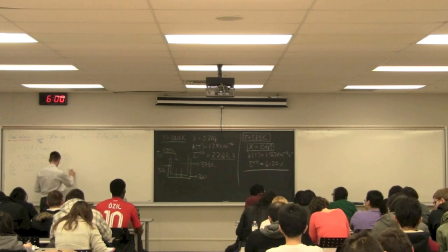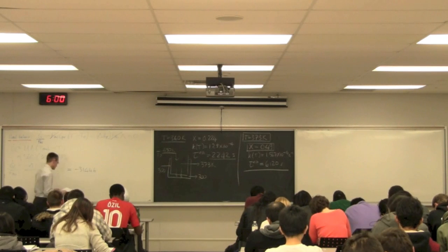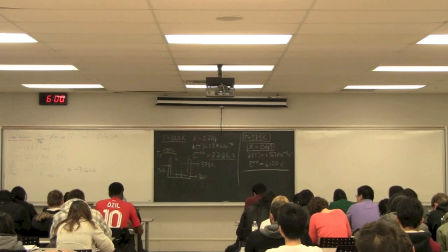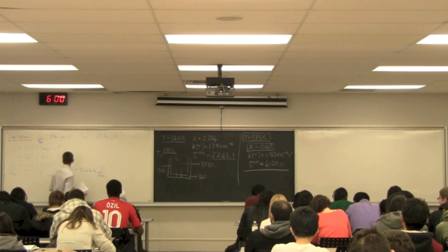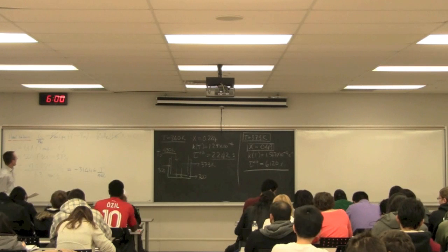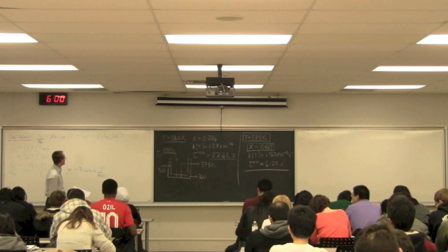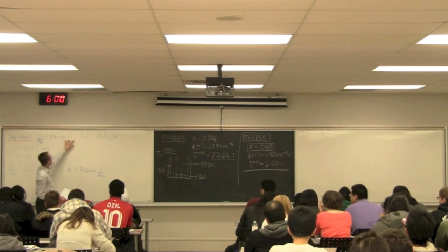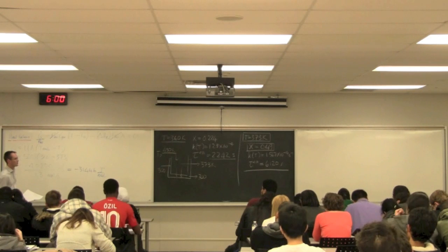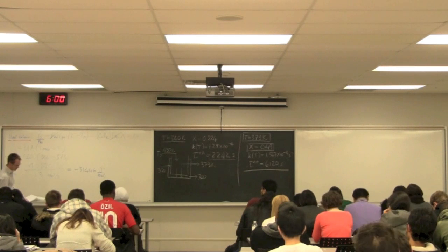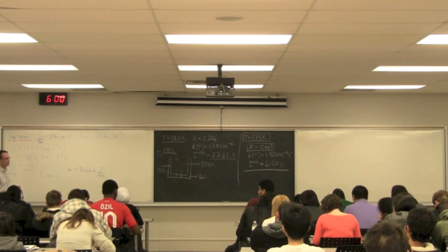And we'll get a value that's equal to minus 31446. So that's joules per mole. So this is heat added or removed. This last term then is heat released by reaction. Anyone got an interpretation for this Cp times T term here? That's enthalpy coming in and out. And if it's positive, we've got more heat flowing into the system and leaving. If it's negative, we've got more heat leaving.